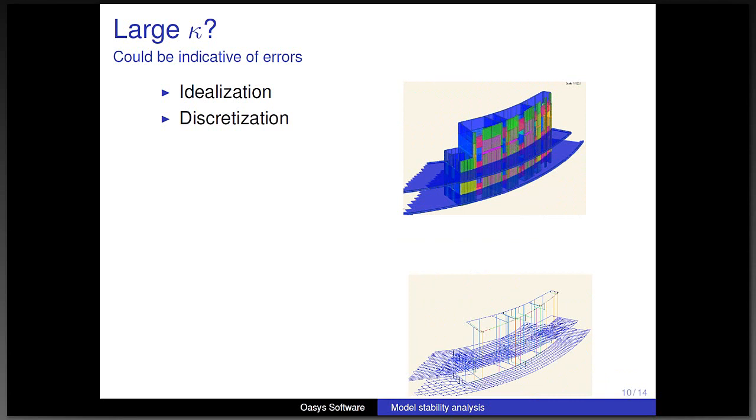So we've got cores modeled as sticks, the shear walls modeled as sticks, which are beam elements. And if, for example, this model had been imported from BIM or CAD, and the lines were faceted in such a way that you end up with really short beams, then because they're modeling cores, the beams also tend to be quite deep. So you essentially end up with a disproportionate amount of stiffnesses in your stiffness matrix.